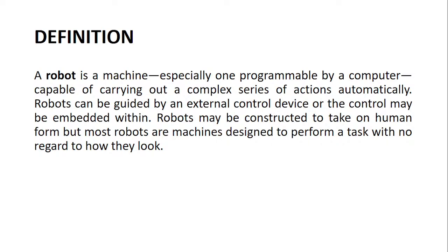It identifies the object, and we have already trained the robot to detect that object. So it will activate the camera and look around for the object. Once it recognizes the object, next comes localization. Next, the robot needs to find out where it is, what is the origin location of the robot, and then it needs to determine the location of the object that it needs to pick.